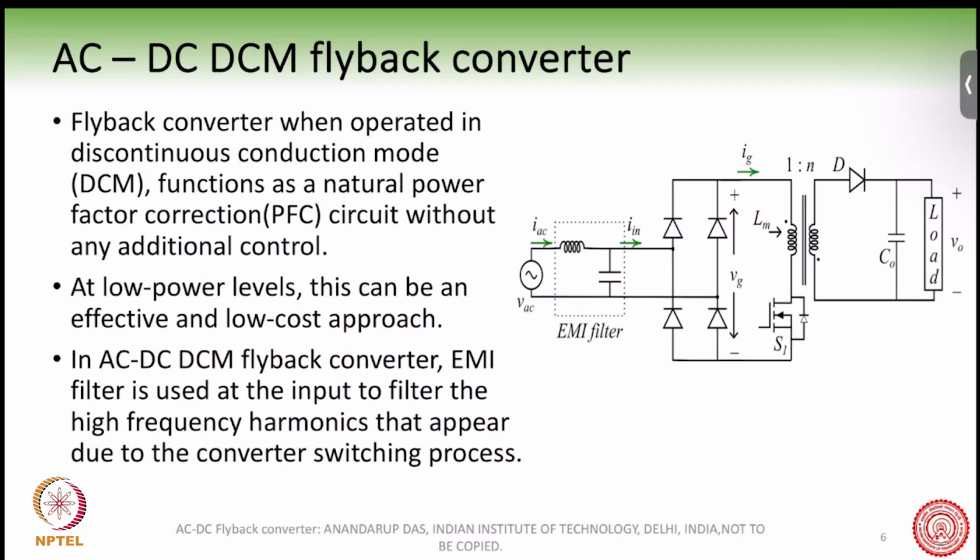Now, the flyback converter, when it operates in DCM, functions as a natural power factor circuit without any additional control. And at low power levels, for example, for this kind of LED drivers, where the power level is typically less than 100 watt, this can be a very effective and low cost approach.